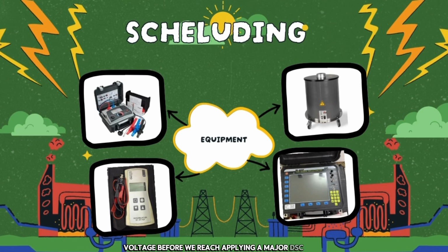So for the left bottom, we call it on-site, or the easiest way, TDR, or time domain reflectometer. This is our radar system. Its function is to transmit a low voltage electrical pulse down the cable and look for reflection caused by the impedance change.